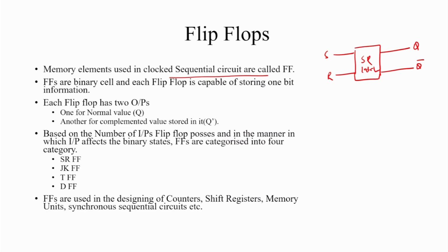This SR latch is made up of 2 cross coupled NAND gates, and when there is no clock input, this is a latch. When we provide a clock input to this flip flop, it works either at the positive edge or the leading edge, and the input change is reflected only on the arrival of the next clock pulse. If an input change occurs during the clock, the output or next state value of the flip flop does not change. Once the next clock starts, the change is reflected.